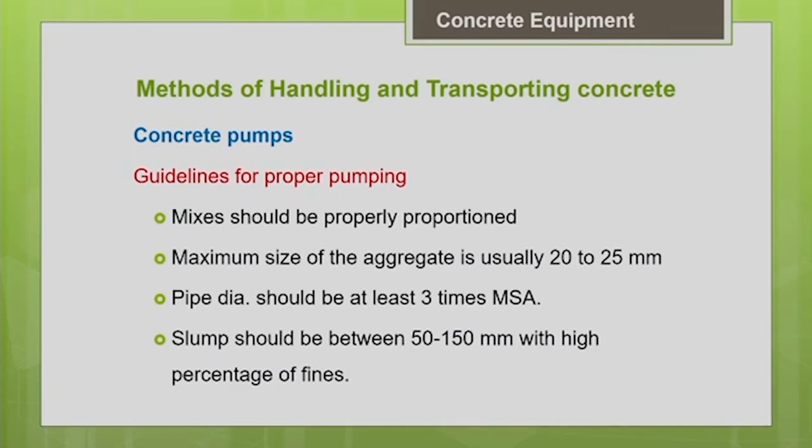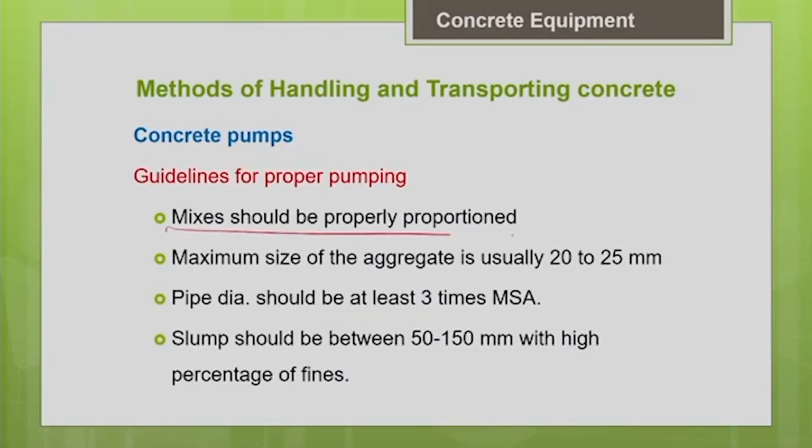If you decide that you are going to go for the pumping method for the concrete placement, that decision has to be made even during the mix design itself. While you proportion the mix, you should decide about the concrete placement method. If you are going to use the pumping method for placement, accordingly you have to design the workability of the concrete so that it can be easily pumped. The mix should be properly proportioned from a pumping perspective.